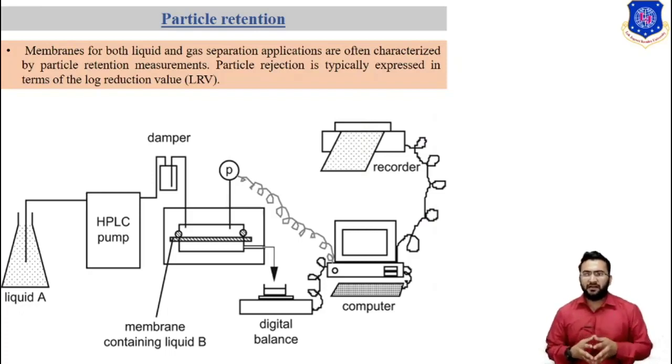Particle retention can occur by both depth capture throughout the thickness of the membrane and surface capture mechanisms. Measurements of particle retention are not without ambiguity. The relationship between the actual geometric dimension of the membrane or filter and the particle size being retained is most tenuous if the filtration occurs throughout the filter depth. This is due to the variety of depth filtration capture mechanisms that facilitate the retention of particles smaller than the openings in the filter structure. These conditions are particularly pronounced in gas filtration.